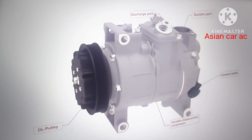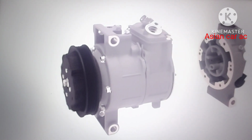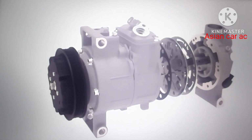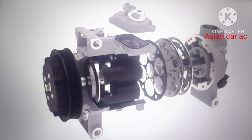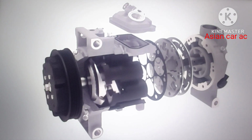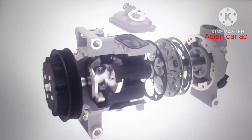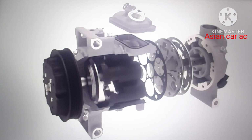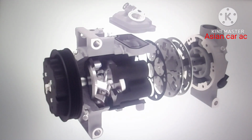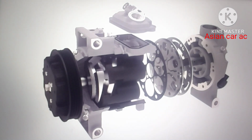The compressor is usually driven by the engine using a drive belt, with a magnetic clutch being used to engage and disengage the drive to the compressor. For some systems, a DL pulley is used that continuously drives a variable displacement type compressor, and for electric and hybrid vehicles, the compressors are driven by electric motors. To provide lubrication, a specific amount of special compressor oil is added to the refrigerant. The compressor creates a high pressure at the discharge port and a low pressure at the suction port.